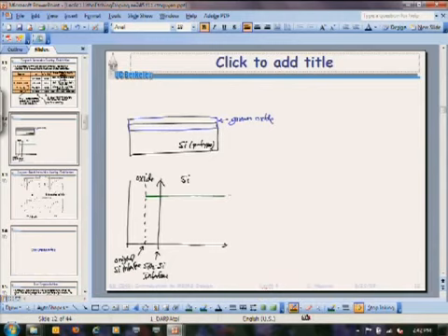Okay, I guess I should label my axes here. Call that x, which is the distance into the silicon. This axis here is concentration, in this case of boron. Okay, so this is what I start out with. This is my starting thing. So now I grow this oxide, and that oxide moves this interface front to here.